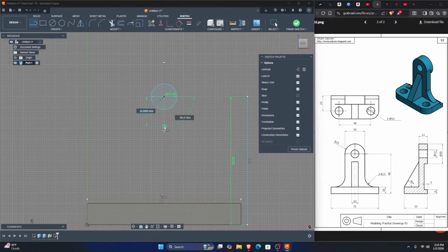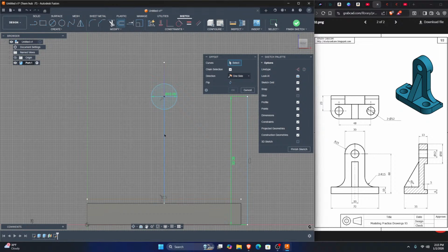I'm going to go ahead and make another solid line. I'm going to connect it here. And from the center, the width, I'm going to offset it by 15 millimeters. Sorry, that's our construction line. Don't need that anymore. I'm going to offset with the O key by 15 both directions. So I'm going to do -1.5.